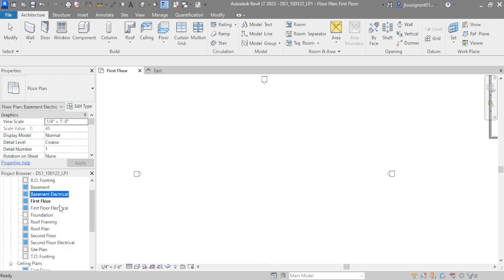And then the electrical plans. One of my things that I'm going to cover is I have found it easier to create ceiling plans, aka reflected ceiling plans, aka electrical ceiling plans, as a ceiling plan. So electrical plans from a designer standpoint can be considered a floor plan, because there's times where people need to know where the outlets and switches and such are, in more of a kitchen and bath sense.